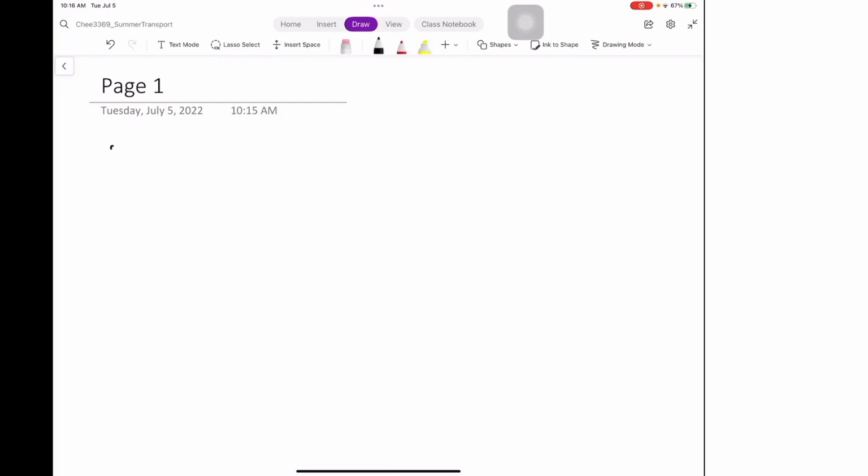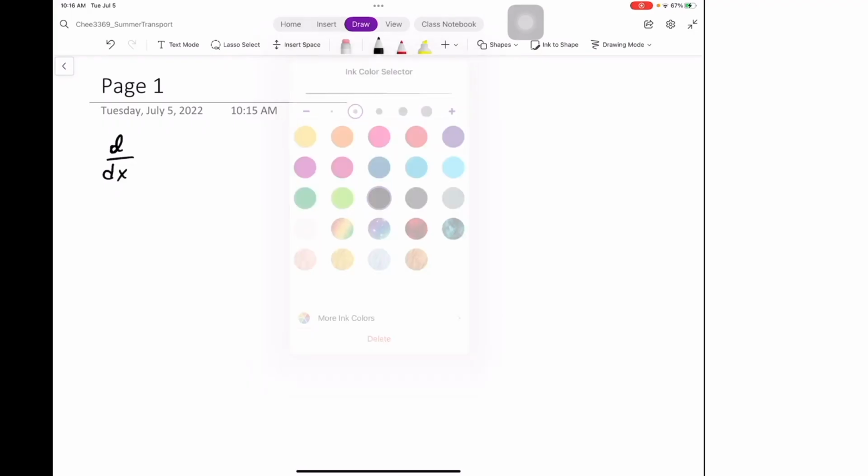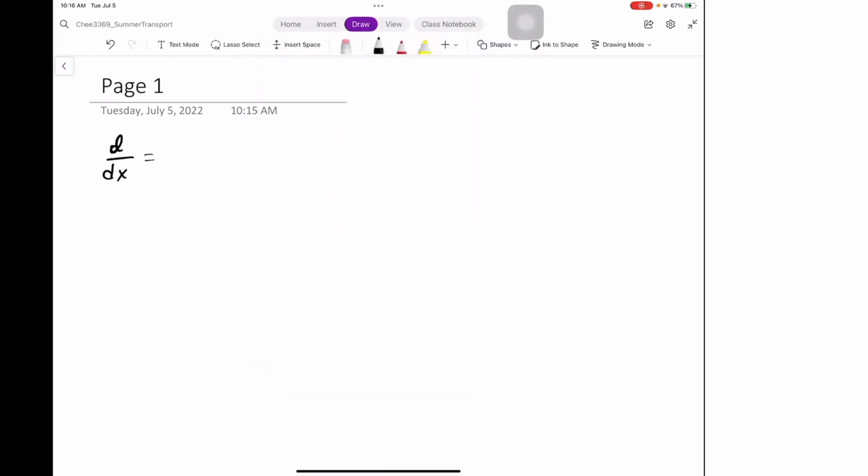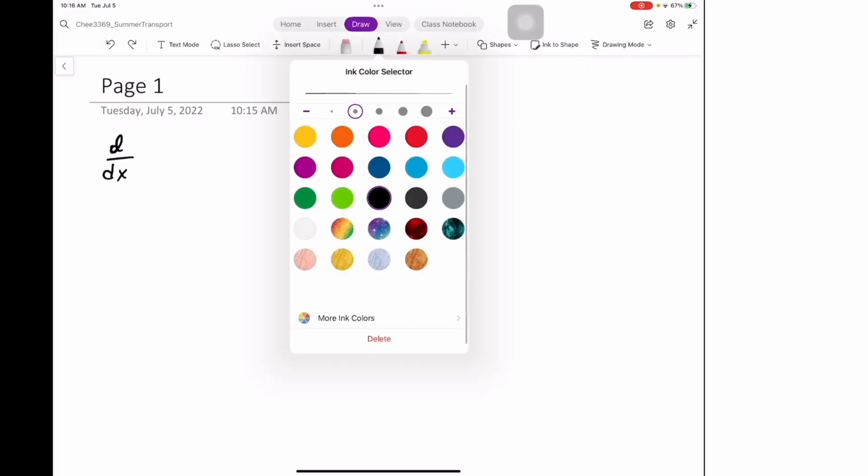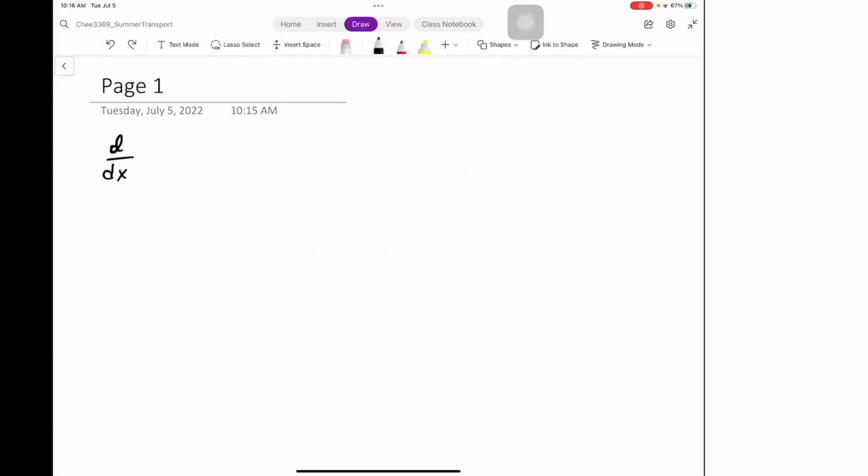Okay, the equation was d over dx, let me make the thickness small, or maybe let's go with this thicker version. Integral from 0 to delta t, vx times 1 minus theta dy is equal to alpha del theta over del y at y is equal to 0.